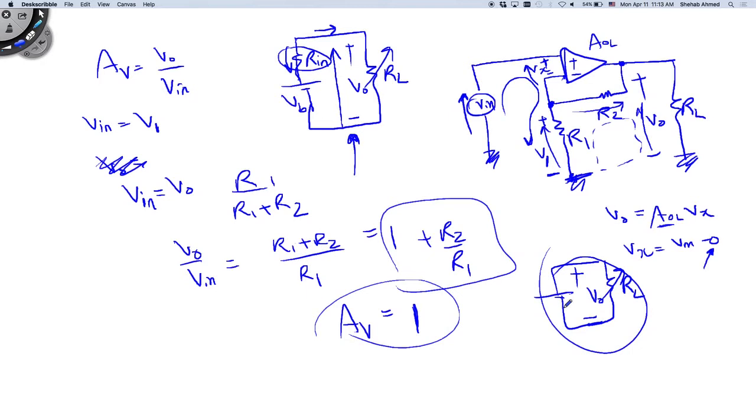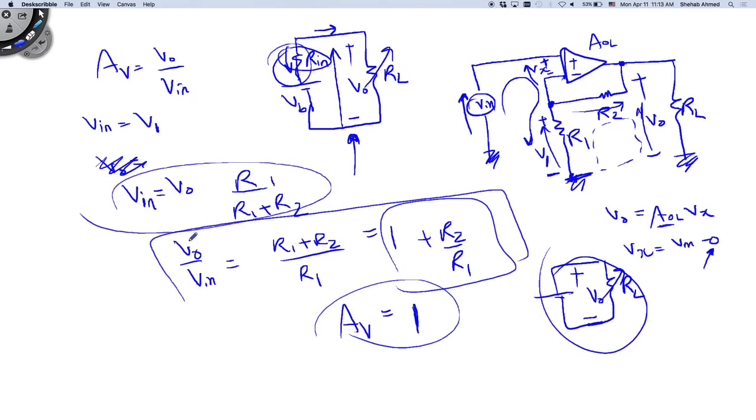In our op-amp discussion, it means that the output voltage does not change depending on the RL changes. If the output voltage changes with RL changes, then the circuit has some output impedance. What is this output impedance? It's equal to the impedance that's in series with the output resistance. Okay? But in our circuits, the way we look at it is, this is the output voltage equation related to the input. The output voltage will never change because of RL. RL is here, it does not even appear in our equation. Okay, so the output impedance of this is 0.